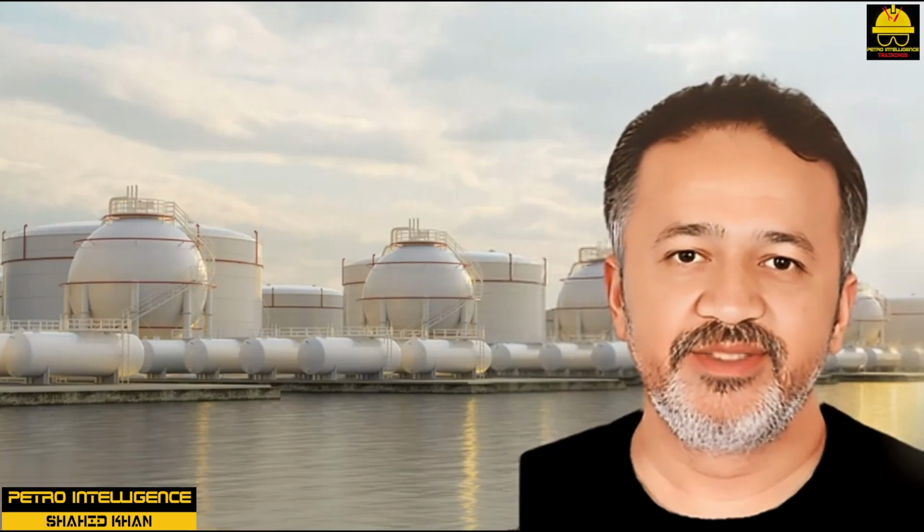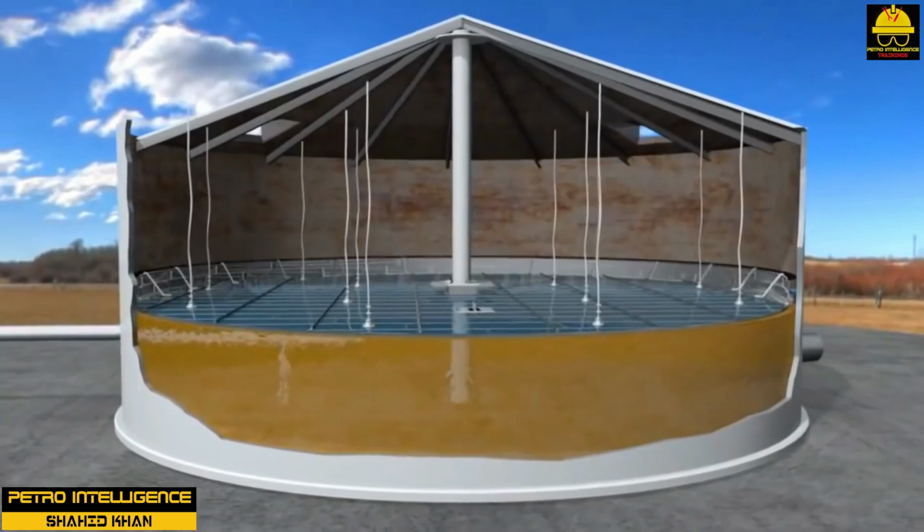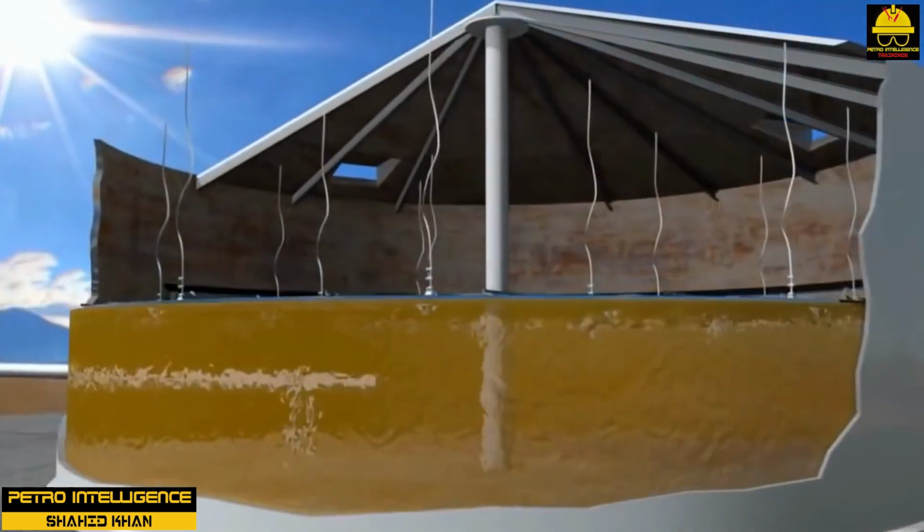Floating roof tanks. A floating roof tank has an open top and a pan-like structure that floats on top of the liquid and moves up and down inside the tank with each change in liquid level, as shown in the picture. A close clearance is maintained between the roof and the shell of the tank.